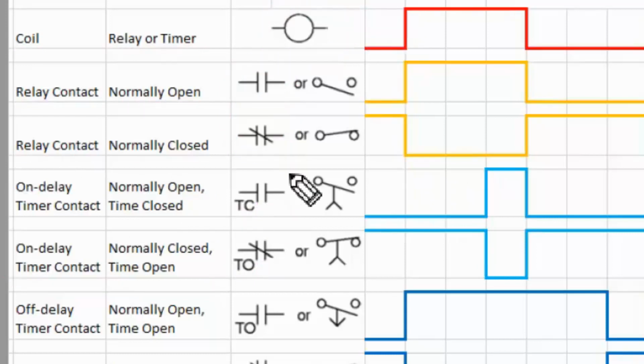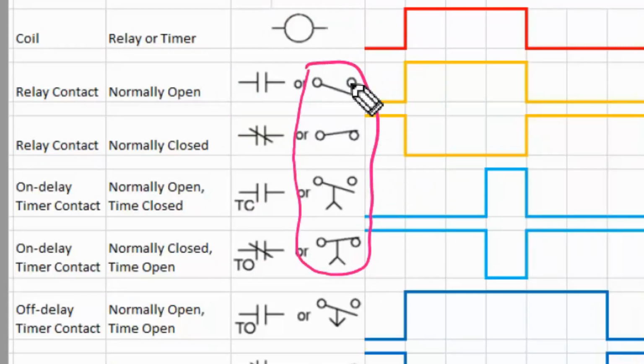The other set of symbols, right, is a little bit different. It's on this part. On this set, you can see they just use a bar, or moving arm, to represent when there's a gap, that's normally open. When the bar is sitting on top here, you can consider that because of gravity it pulled down here, so it made those two circles contact together. So that's normally closed. That's for the relay.